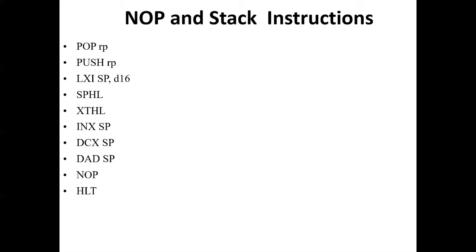Next is XTHL. XTHL is a mnemonic which stands for exchange top of stack with HL. This instruction exchanges the contents of the top 2 locations of the stack with the contents of register pair HL. It is not the exchange of SP with HL. It occupies only 1 byte in memory.